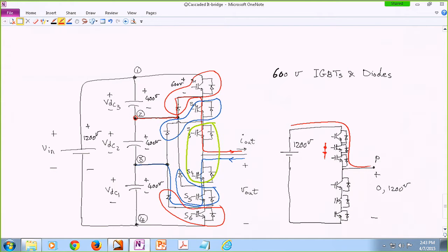Now imagine then this one turns on. So the bottom 2 are on, the top one is handling 1200 volts, but it was a 600 volt IGBT. So boom, it actually smells and you have to replace it. Timing between these 3 transistors to turn them on and off becomes really crucial. So then you have to use some clampers and RC circuit around that to do that.